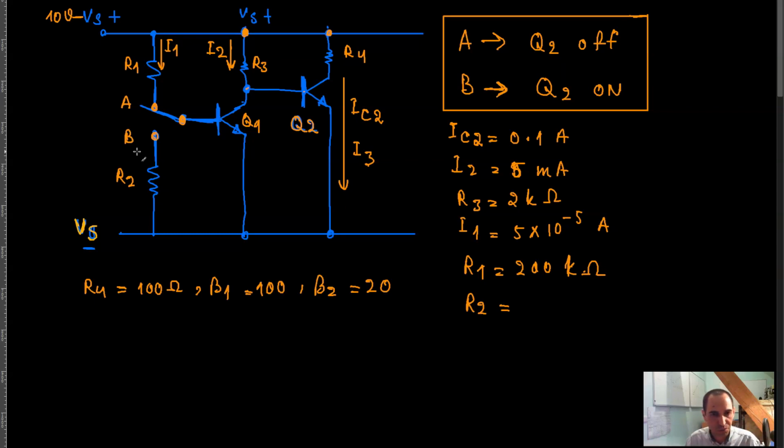10-20 kilo ohm all the way up to 1 mega ohm. You can choose any resistor value that you have in your junk box. And since we chose this resistor value 200 kilo ohm for R1, we can choose the same value resistor over here, and there is no problem there because it's less than 1 mega ohm, right?